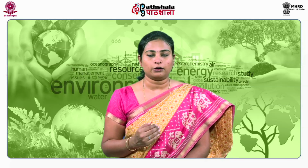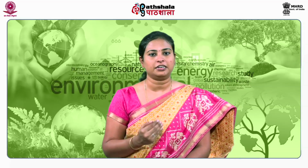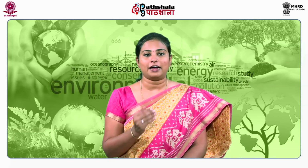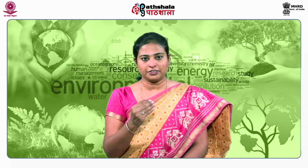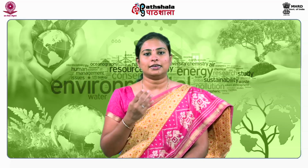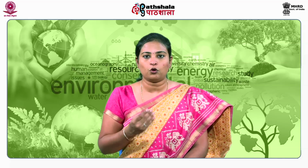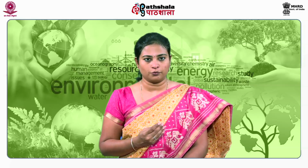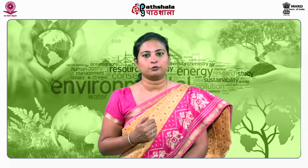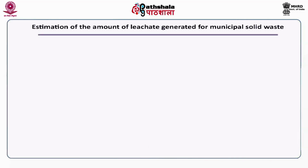Now, let us discuss how to estimate the amount of leachate that will be generated in a particular landfill. There are a lot of factors that greatly influence leachate generation. Some of them are listed below: the amount of rainfall, the amount and rate of rainwater infiltration through the landfill, the potential of waste to absorb water, the amount of liquid waste disposed in the landfill, the weight of the waste after the absorption of water, and leakage via seepage or discharge.